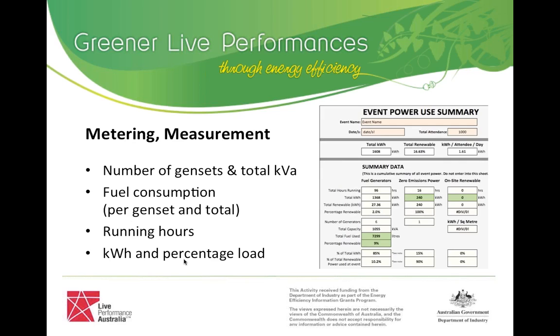There's no use saying, oh, we had this number of generators and we use that much fuel, but you haven't also tracked how long the things were turned on. That completely puts it in context. And the true measure of efficiency, or a true measure of efficiency, as we've heard, is optimizing the power load on these generators. So getting them in that 70 to 80% sweet spot for as much of the time as possible is an important aspect as well.